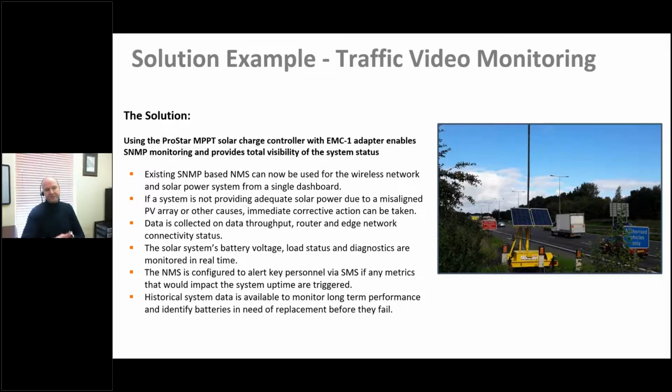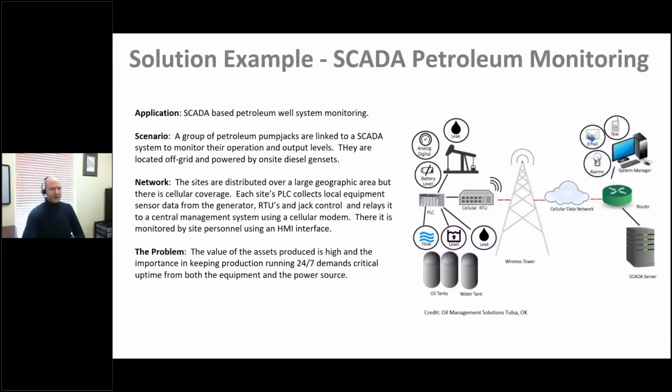It's even common to see these solar arrays are not deployed correctly. They're movable and they're sometimes put in shading, or they're pointed in the wrong direction, so they're not facing south. And these things can be detected early and taken care of.